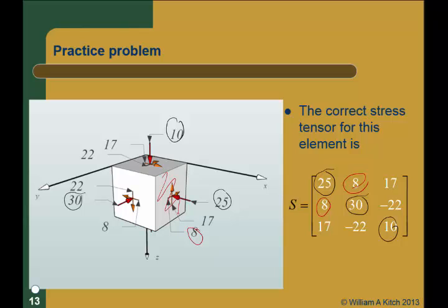It's a negative plane. In this case, negative is positive, and positive is negative. Is that shear stress acting in a positive direction or a negative? Is it acting in the positive axis or the negative axis? It's in the negative xyz direction on a negative plane, so it's a positive shear stress.